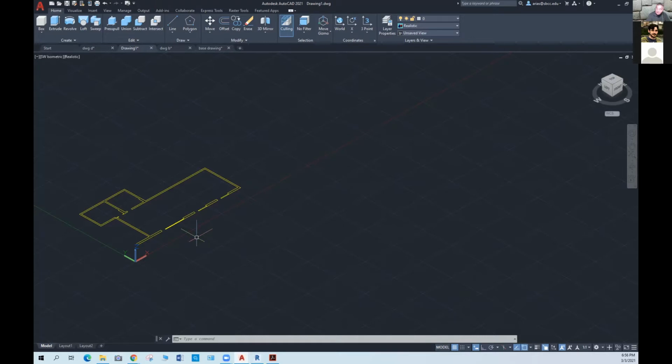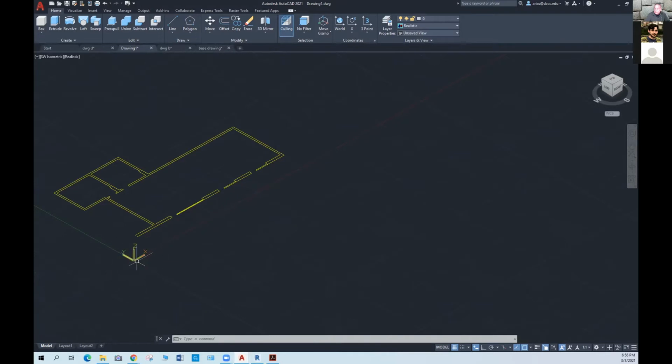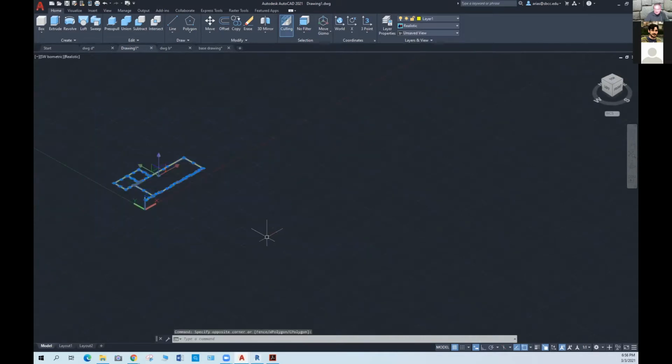Now that said, we can modify the X and Y workspace. So look at the UCS icon there. X and Y is now located on the floor. Let me delete this and let's pretend that we're going to bring that onto a side wall, if I wanted to bring an elevation. So what I'll do now is I will rotate the UCS. I can change the UCS by rotating in one of the axes here.